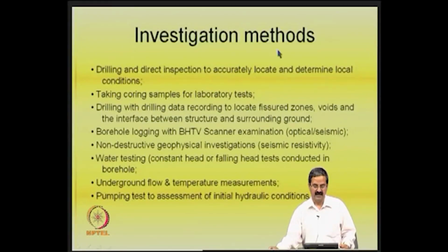In the investigation methods for grouting, you must be able to have a direct inspection. You must go for drilling to locate and determine local conditions, then take core samples for laboratory tests.